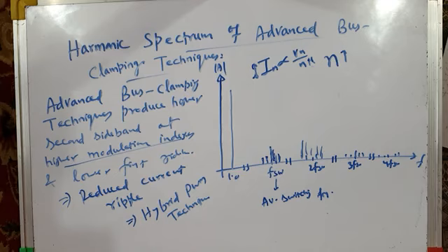In today's lecture we have reviewed various types of PWM techniques which we had already studied in module 2 and module 3 and part of module 4, and we also proved that the space vector PWM technique increases the inverter output voltage by about 15.5%. We proved it mathematically today. And then we discussed the harmonic spectrum of inverter output voltage for sine triangle PWM, which was aided by the harmonic model of the induction motor also. We found that harmonic current is proportional to Vn by n, and we defined a new quantity called weighted THD. Weighted THD is actually the THD of the voltage, but it represents the ripple or distortion level in the current. So the less the distortion level in the current, the lesser the weighted THD will be.